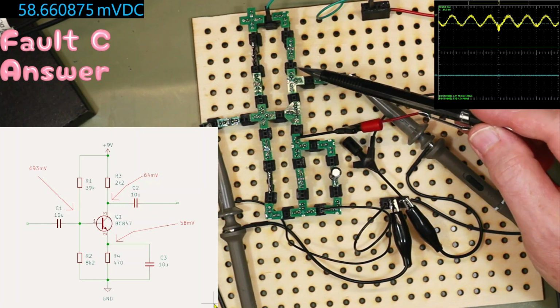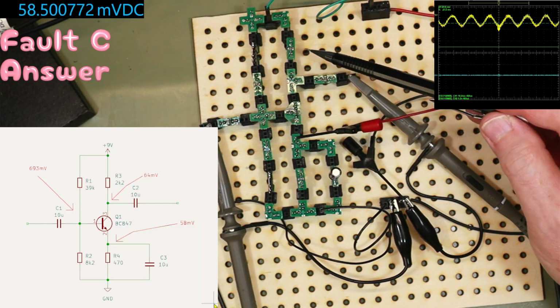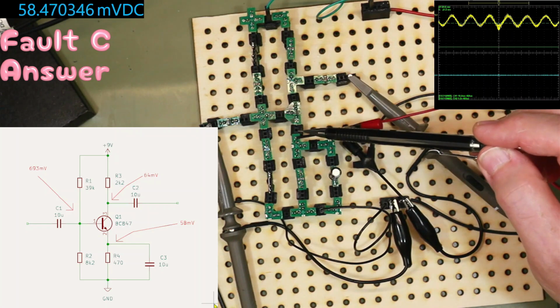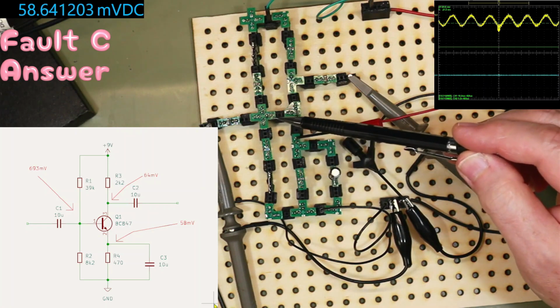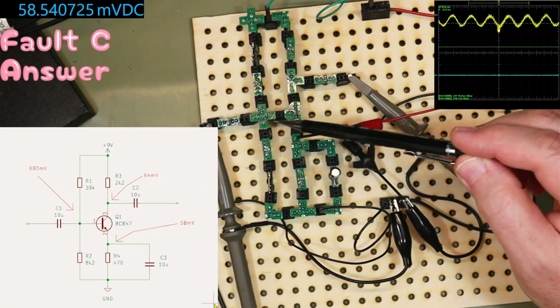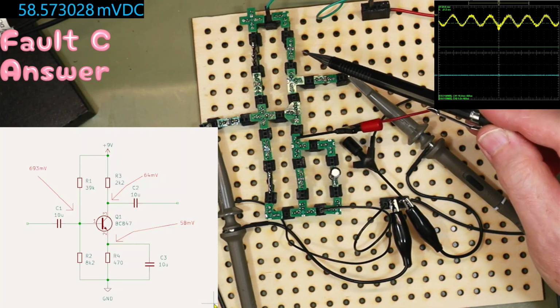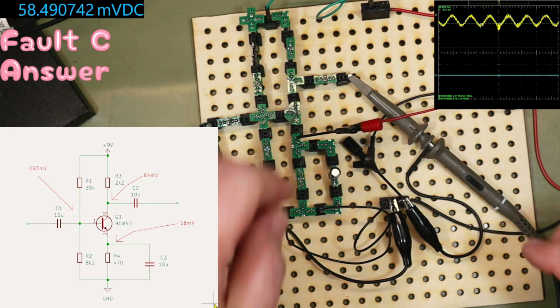So the fact that there is no current down here points to one of two things. It's either a problem up here or a problem down here. Now if we got some current flowing through the base, it must be flowing down here. Something is holding that 0.6 volts above that, so there must be current flow down here. So that would point to the fact that the collector resistor R3 must be open circuit.